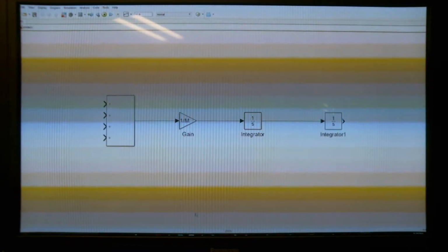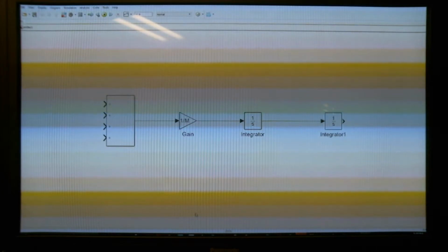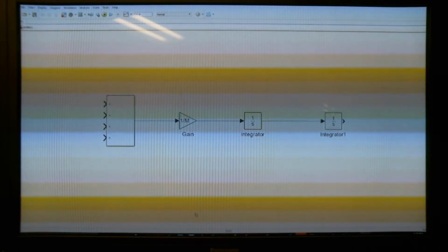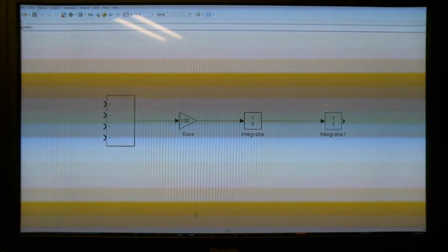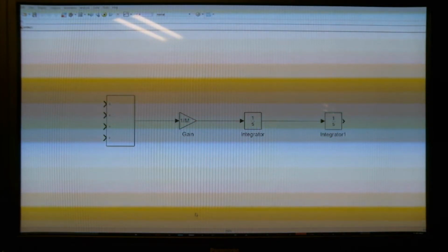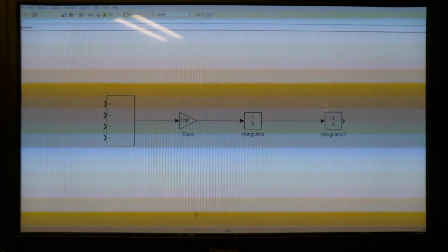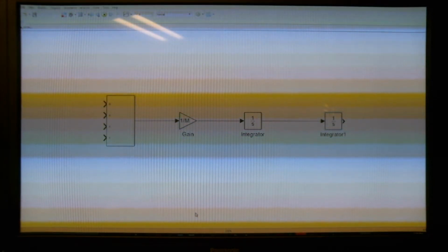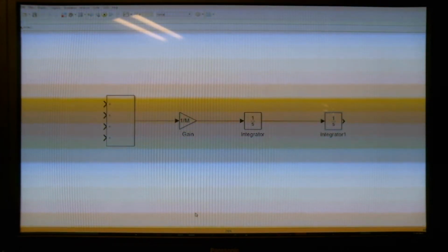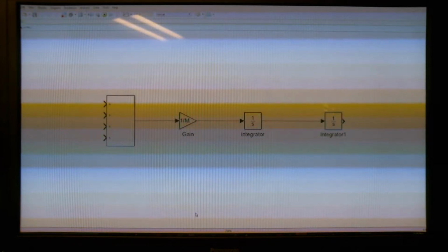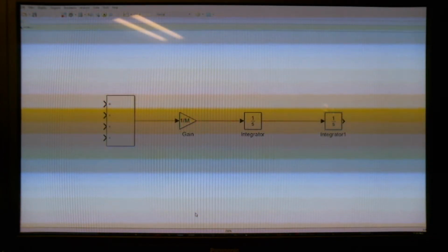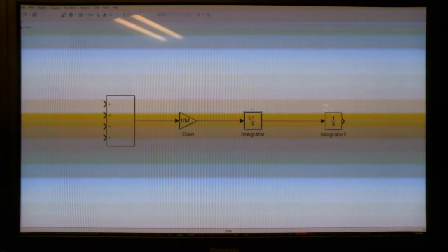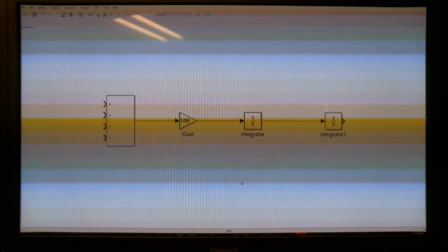So if you have a damping coefficient on your bouncing ball and you simply use these two integrator blocks one after another, and simply have them bounce, you're going to see that it never actually stops bouncing because of the error inherent in the integrator blocks, because they add up and gain to each other. However, there is a workaround for this called the second order integrator block.